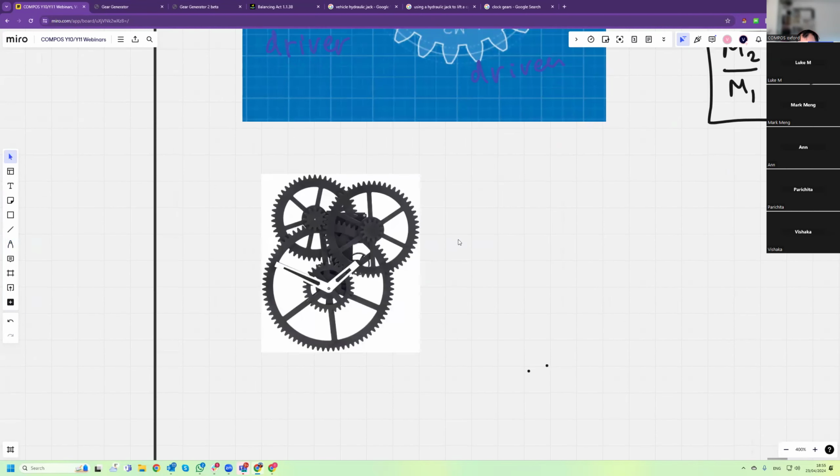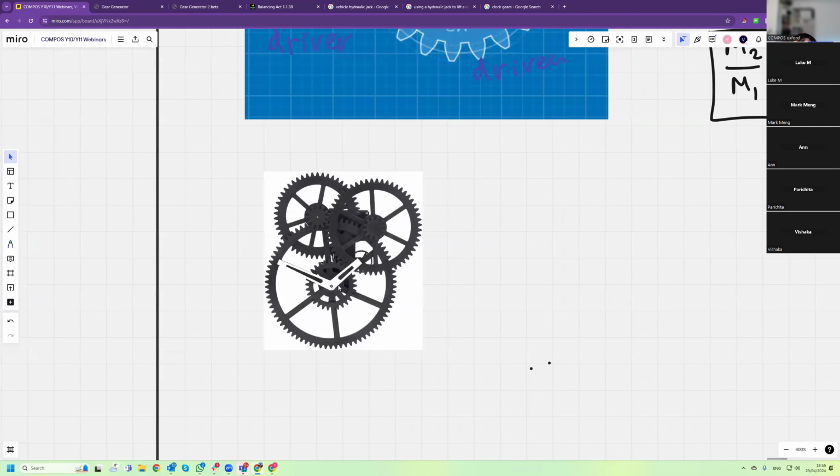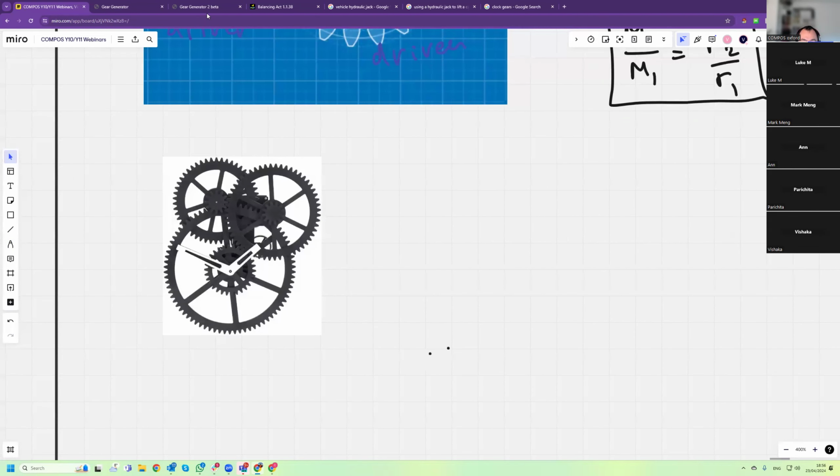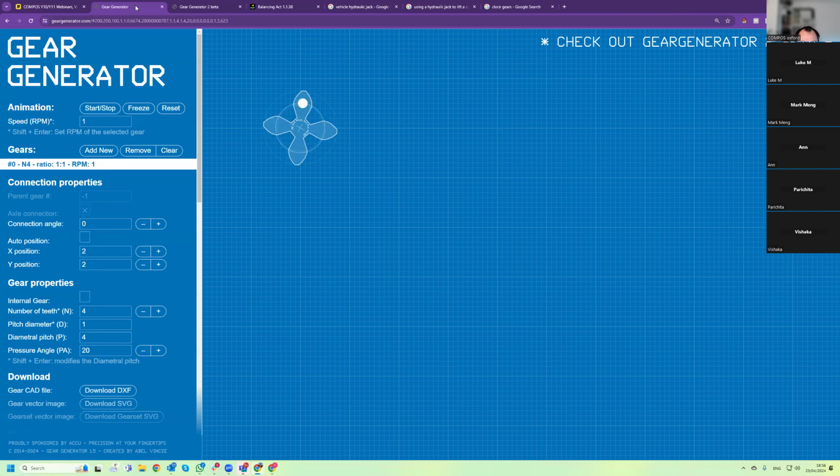You just need to count the teeth. All right, so I'm not going to do that, but you can do that later. But what I need to do is I need 3 different wheels rotating at 3 different speeds. So this represents the second arrow of the clock. So it goes around every minute. So that means 1 RPM, literally. That's what it means, 1 rotation per minute.